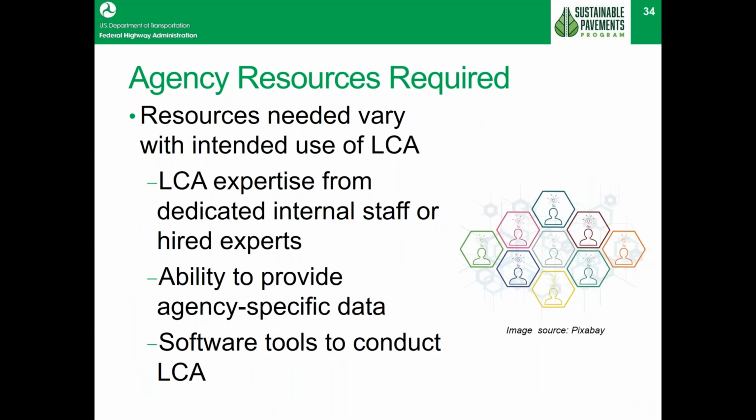So what are the resources required for an agency to use LCA? Resources needed vary with how the agency is going to use LCA, but they typically rely on LCA expertise from dedicated internal staff or hired experts. There are a number of commercially available LCA software tools and also spreadsheet-based tools that include lifecycle inventory data sets for pavement that can be used as a starting point to develop LCA models. And some state highway agencies have developed their own customized LCA software tools with agency-specific default background data.